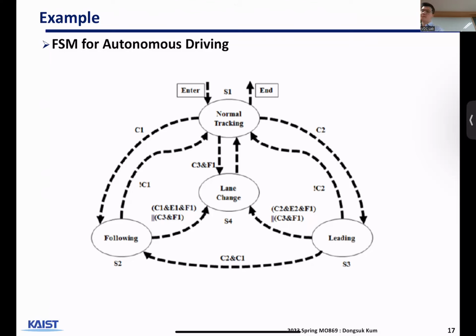And then you will need to be able to handle roundabout, parking, lane merge. There are these scenarios, and you can make these a finite state machine logic. That way, for each state or each mode, you can design a proper motion planning algorithm for that mode, for that scenario. Okay.